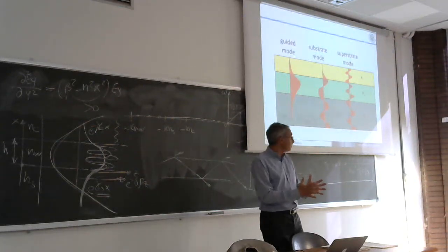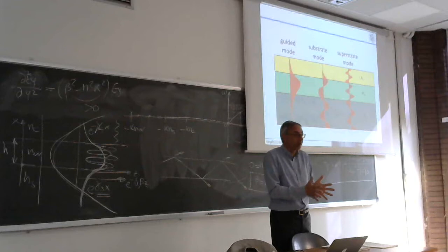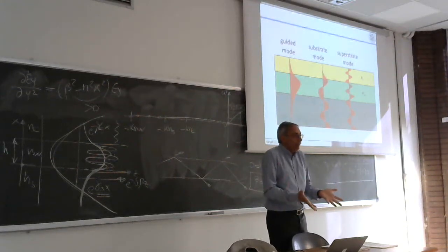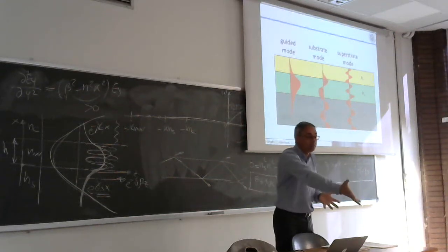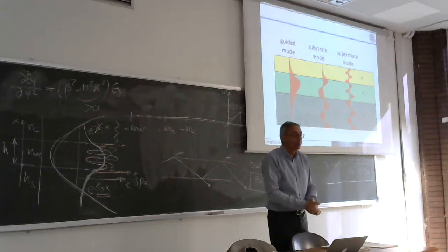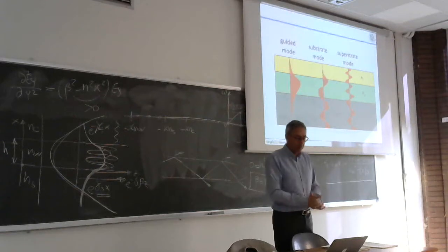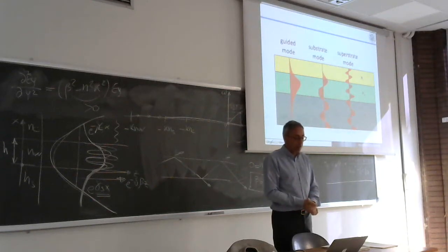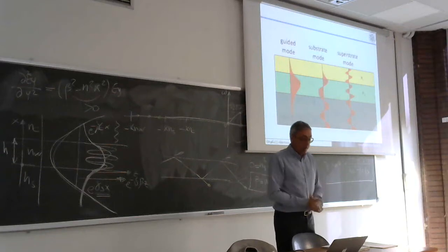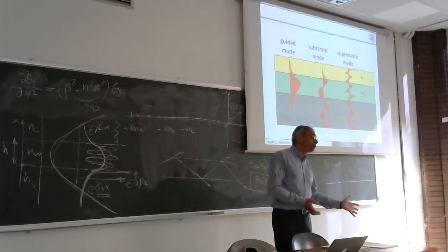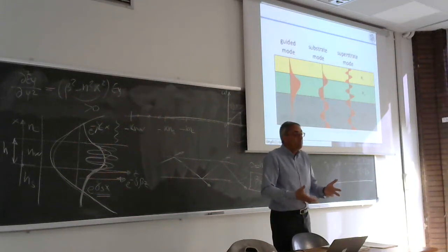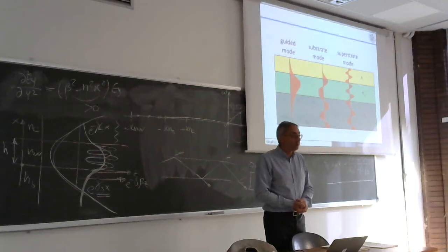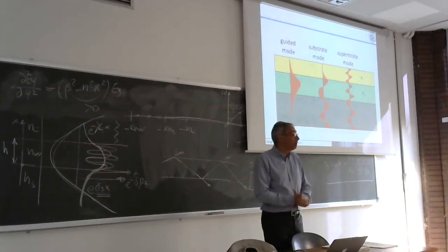So, for example, in integrated optics, where all the components are close to each other, maybe the mode is not guided, but arrives at the next device, the next discontinuity. I don't want to go too much into detail, just to let you know that there also exists this strange condition that cannot be considered totally radiative, but is a badly guided mode. Let's call it like this. These are the names: leaky mode.